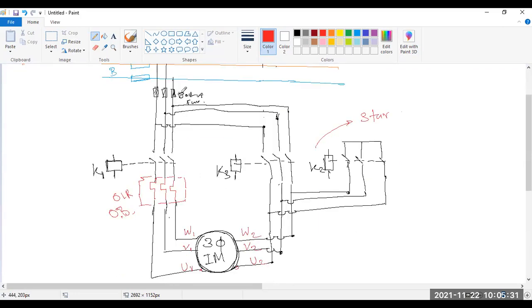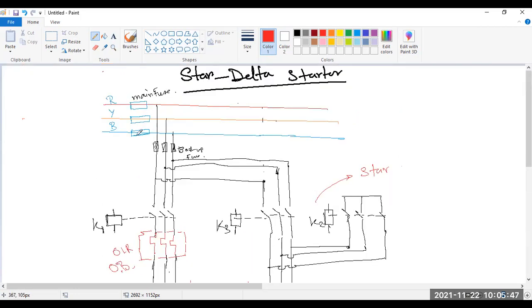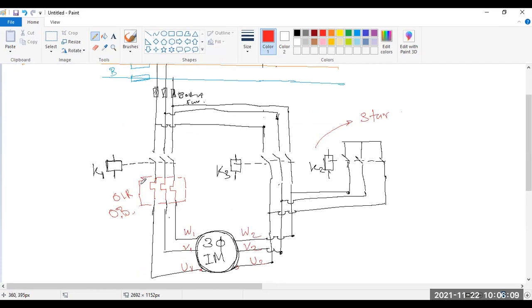This is the first circuit breaker. There may be more circuit breakers, but generally this type of breaker is used. First fuse, maybe the mainline fuse, backup fuse, and this is the main fuse. Its rating is very high. But for a particular individual motor, if your rating is say 10 ampere, you have to put a 10 ampere fuse, or maybe 64 ampere, then you use that. Okay, then it comes to the breaker.